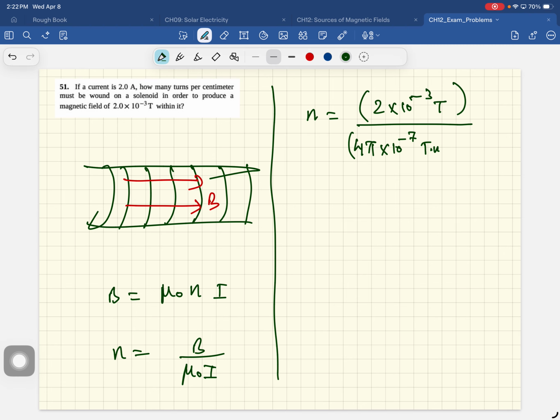A toroid has 250 turns of wire, so there are 250 wires coming out. So the total current is 250 times I, mu naught times N times I. So B is mu naught N divided by 2 pi R times I. Okay, and we'll calculate it for 8.9 centimeters.